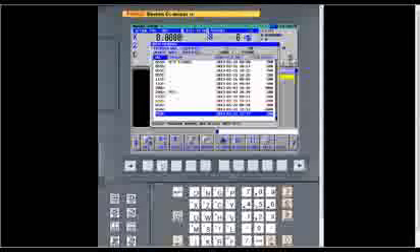Okay, good. All right, Jody, how about this one? Can the G-code output use G70, G71, G72? No, I'm sorry. Say that again, Mark. Can the G-code output use G70, G71, G72? Yes, it can. It will use those cycles.